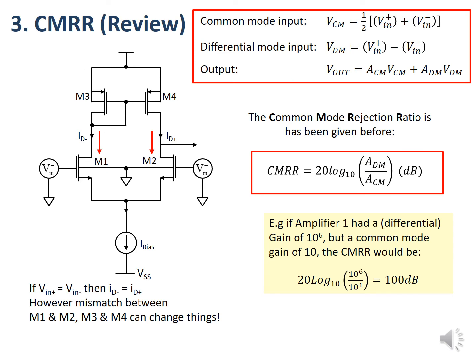We've talked already about the common mode rejection ratio and how we want to make sure that the common mode is reduced as close as possible to zero. So we're looking for a very low value of the common mode gain and a very high value of the differential mode gain. We've defined the common mode rejection ratio as one divided by the other, and then the decibel calculation. The inherent origin of this is caused by very slight mismatches in the transistor design of the differential input stage.